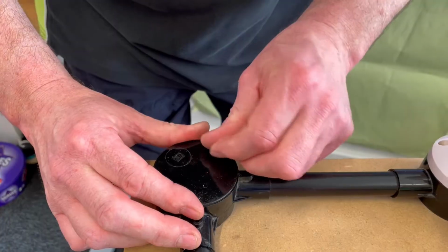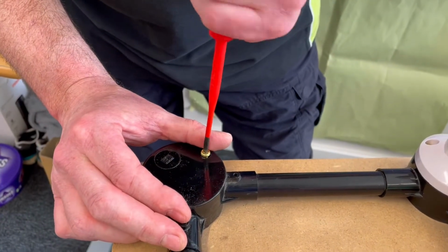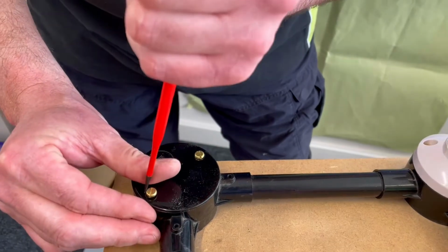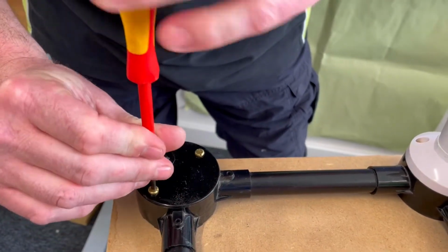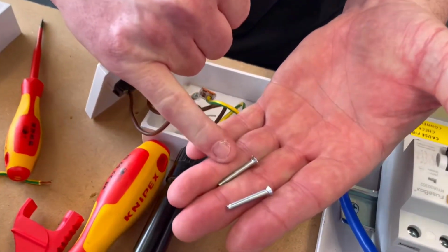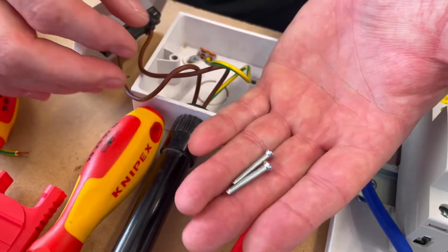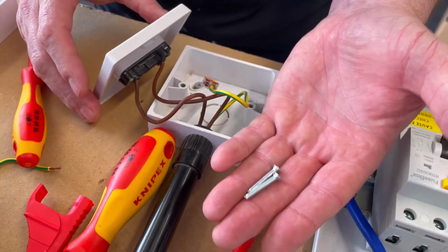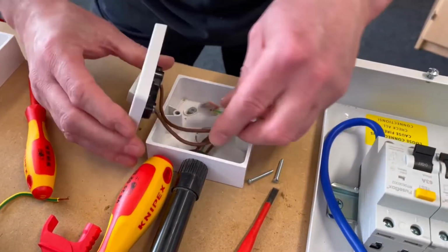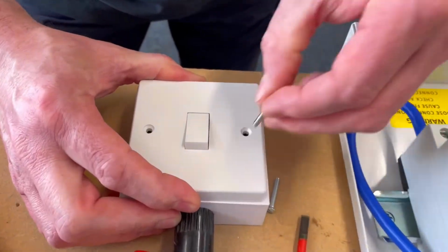Once we've got that one into position, we can then reassemble our light switch next. So that will need to screw down. So all of these need to be in position before we can carry out that insulation resistance test. So light switch next. So now to hold the light switch in position, we're using these 3.5 machine or box screws. So they're different to what we had at the top. So we've got to make sure we get the correct screws in the correct position. Just going to make sure that we curl the cables in neatly into the back of the box, and then we'll hold that in position.